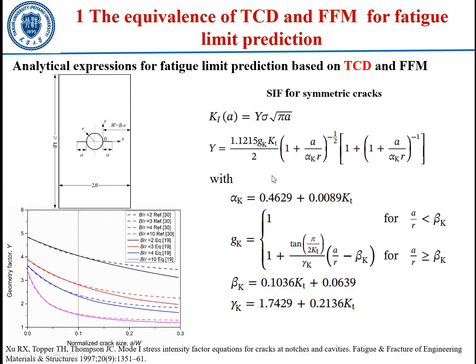This figure shows the stress intensity factor used in the FFM. From this figure, we can see when the crack is short, the stress intensity factor obtained by this equation agrees well with the FEM results in the reference. This is enough for the FFM because the critical distance is usually small.